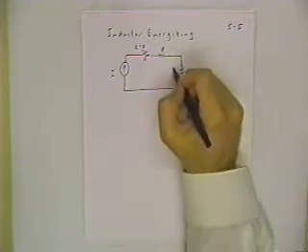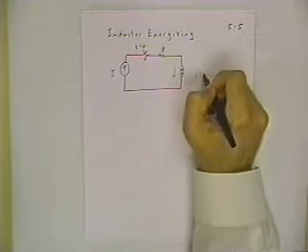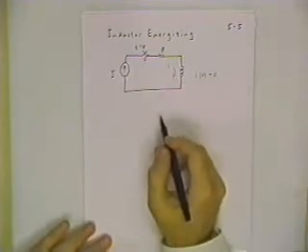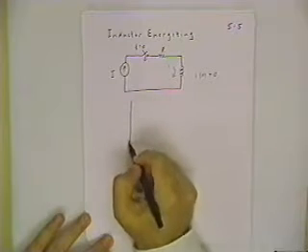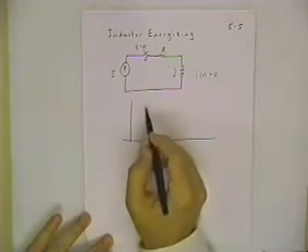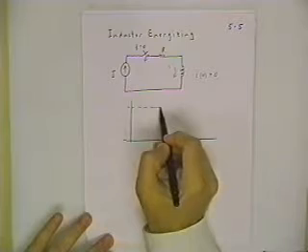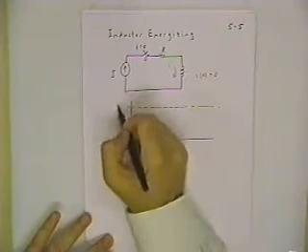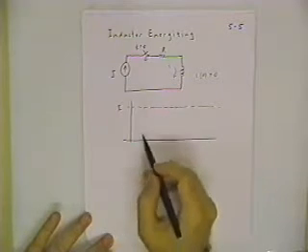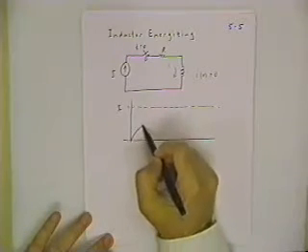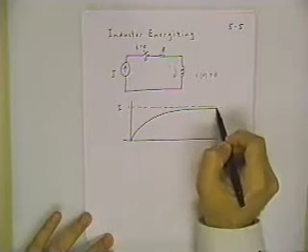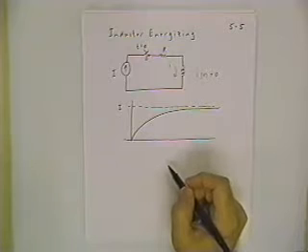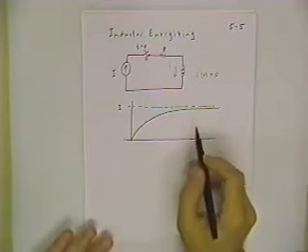But if initially the current in this inductor is equal to 0, it's going to take a certain amount of time for that current to build up. So just appealing to your intuition now, what we have is a capacitor charging situation to think back to. This inductor energizing up to a full current of I is going to follow the same basic physics, because after all the basic VI equations are the same, derivative of one relating to the value of the other.